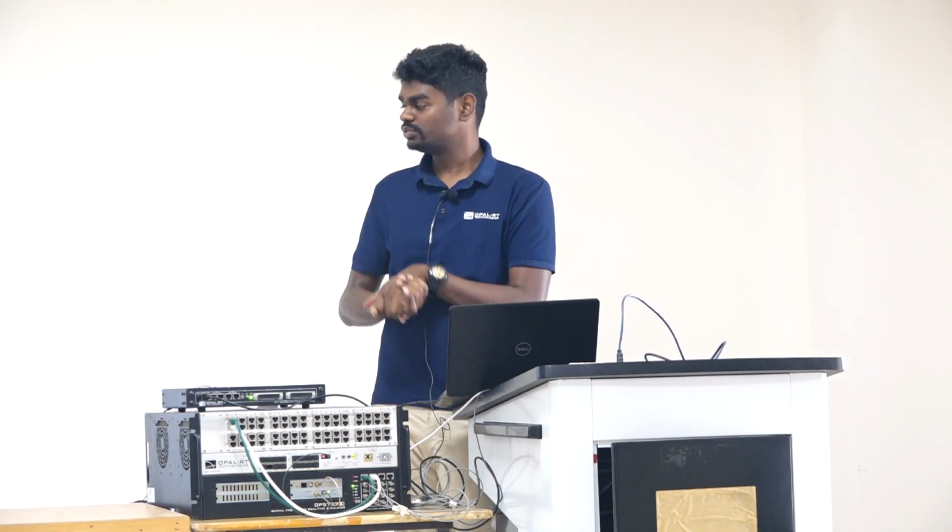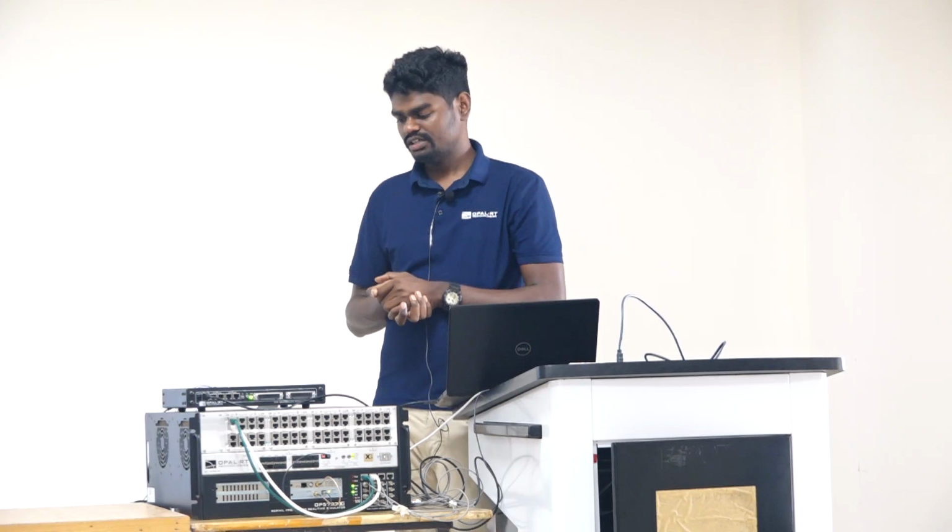This is how you modify your simulation so that it is ready to be tested in HIL. You go through the basic procedures I said, grouping into subsystems, changing the solver and so on, and you configure analog outputs and digital inputs for this application. So now this is what the plant model is all about.